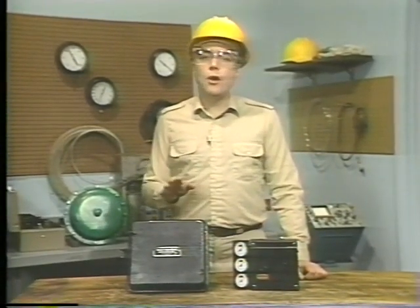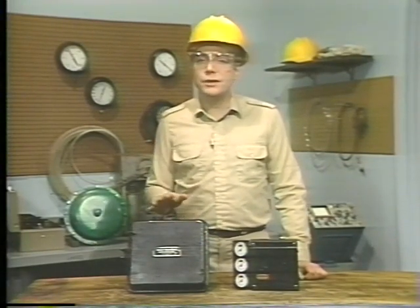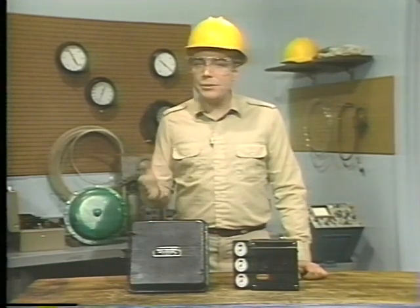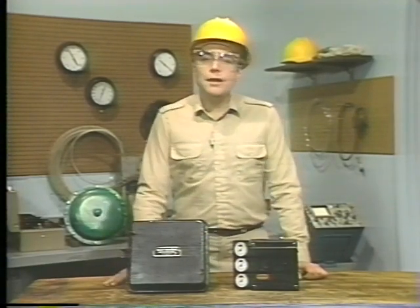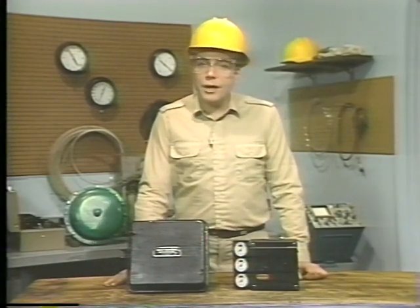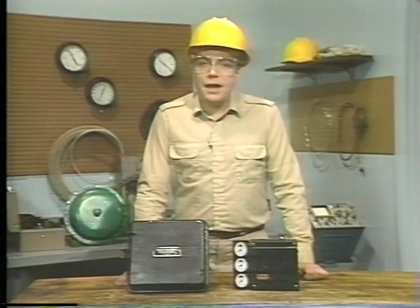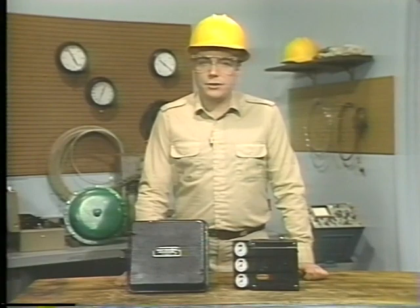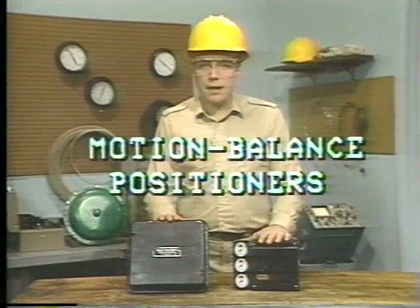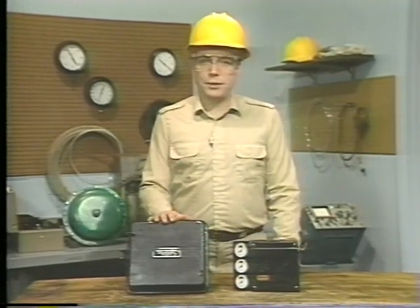You see, the positioner knows when the actuator has moved the final control element to the correct position because there is a mechanical feedback link between the actuator and positioner. You'll see the importance of feedback in controlling actuator travel as we explain the operation of positioners. In this part of the program, we're going to look at two types of positioners: a force balance positioner and a motion balance positioner. We'll start with the force balance positioner.